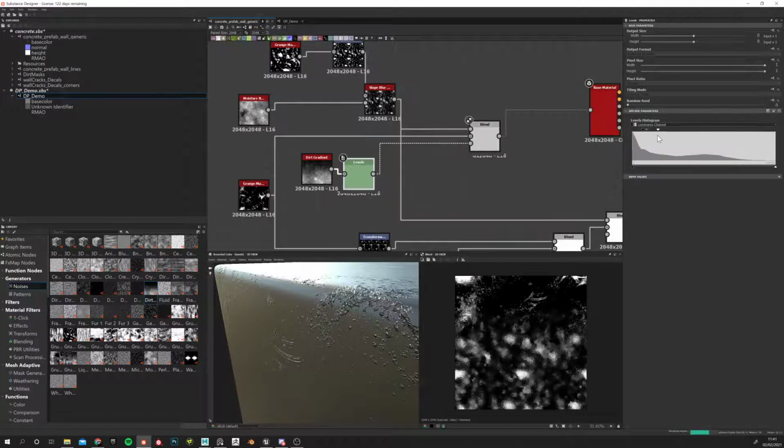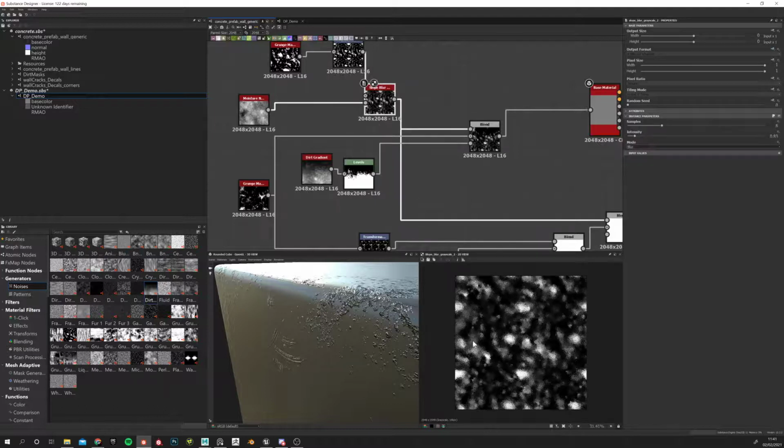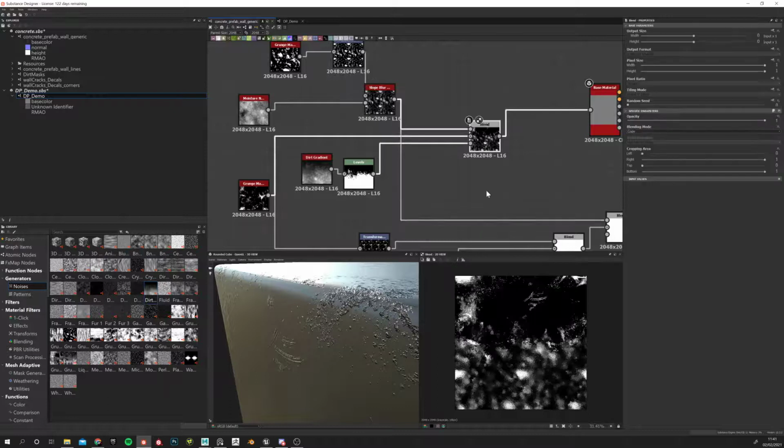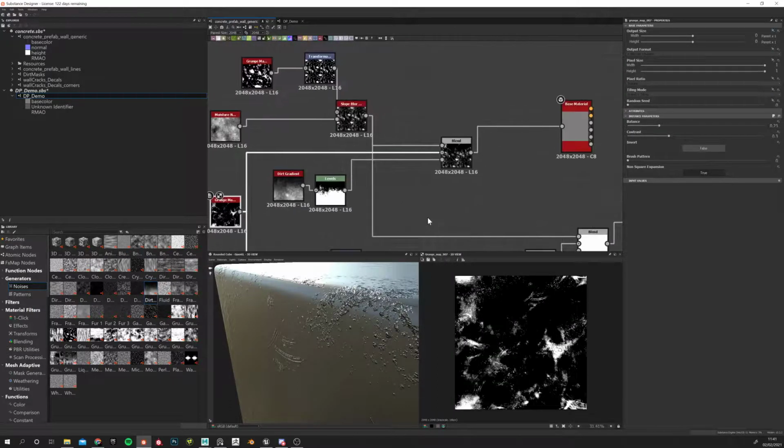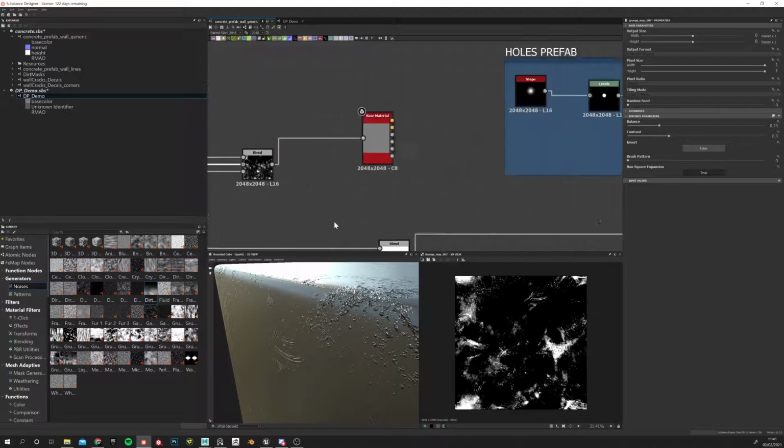You can make it look a little bit more like this. You can see that halfway through. By playing with the levels, I'm only passing half of the texture here where the white is, and the black says no, keep the background, which is essentially this one here. Okay, so once you have that, then you can just start building your material all the way through like that.